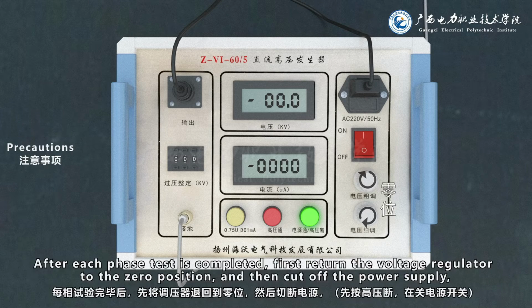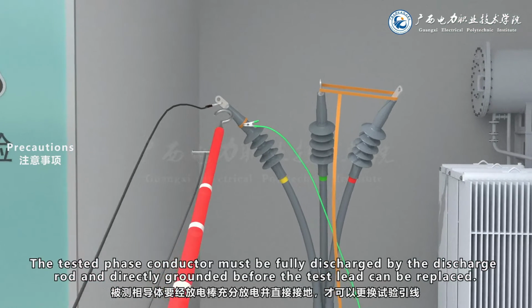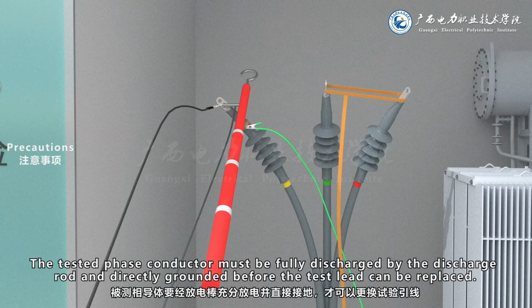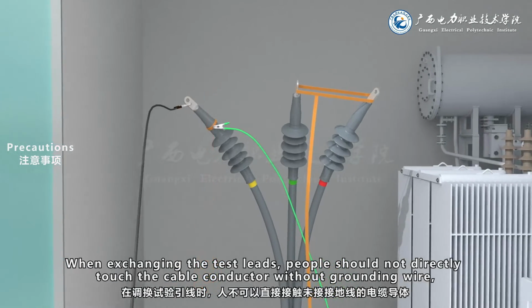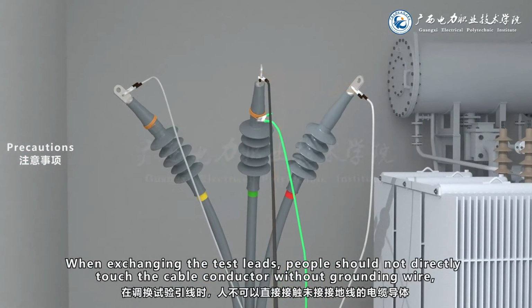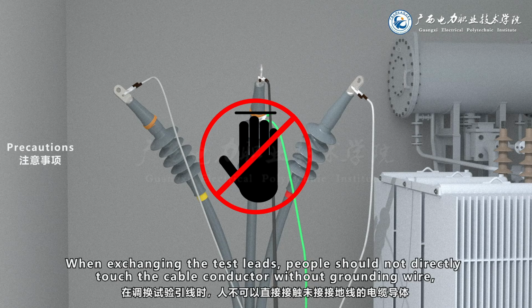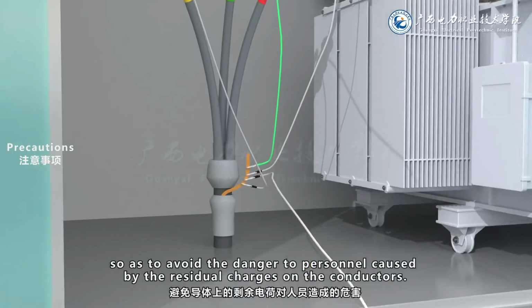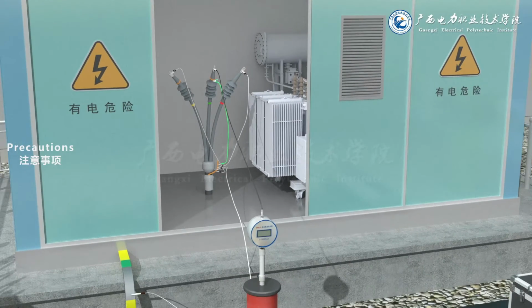After each phase test is completed, first return the voltage regulator to the 0 position, and then cut off the power supply. The tested phase conductor must be fully discharged by the discharge rod and directly grounded before the test lead can be replaced. When exchanging the test leads, people should not directly touch the cable conductor without grounding wire, so as to avoid the danger to personnel caused by the residual charges on the conductors.